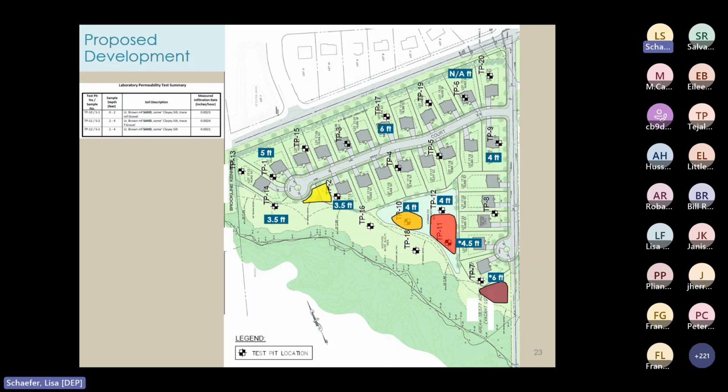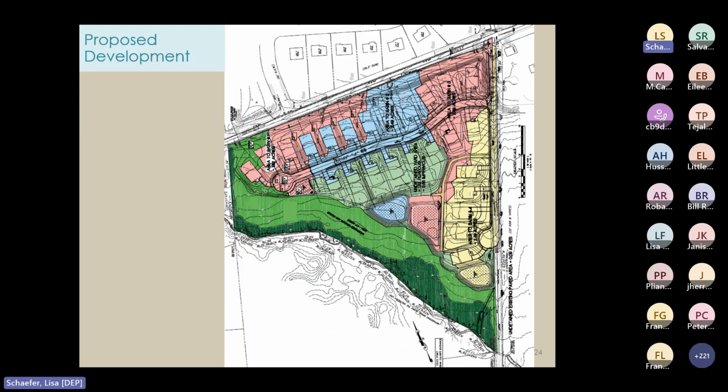All right, so now I want to look at the drainage area map for the proposed condition. And here it is. So hopefully you can see the contributory drainage area to each of the under-drained small-scale bioretention basins is less than the allowed maximum of 2.5 acres, which is specified in N.J.A.C. 7:8 under subchapter 5.3(b). So that seems to meet one of the requirements for GI.